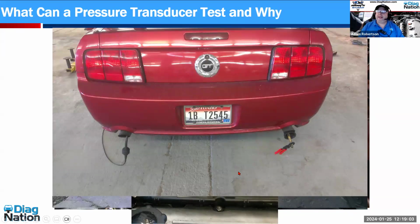Now, there's been a lot of talk in the Facebook pages and some of the other diagnostic pages out there about how you look at exhaust pulses when you have dual exhaust. And look, to keep it as simple as possible, I've been pretty successful with this. I basically took my smoke machine cone, plugged it off, and I read my pulses here. All right. Now, once again, take some practice, but there's another option for you.